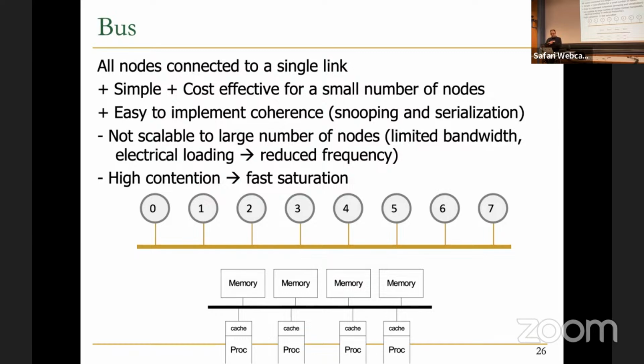And at each time, assuming that your bus is not hierarchical, so you have only one single bus, there should be only one driver to the bus. So not more than 1 node should access the bus to write or drive it. There can be many other nodes that read it.